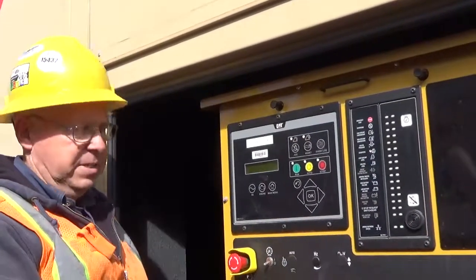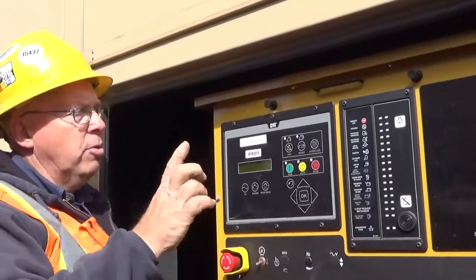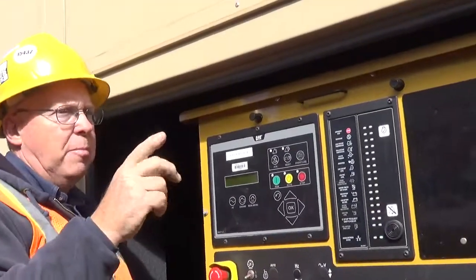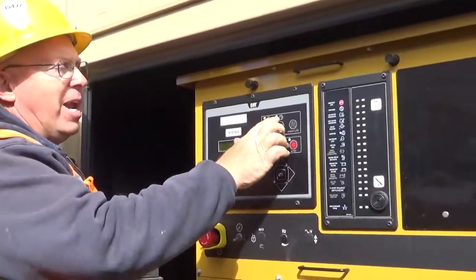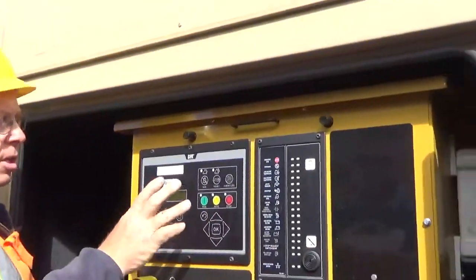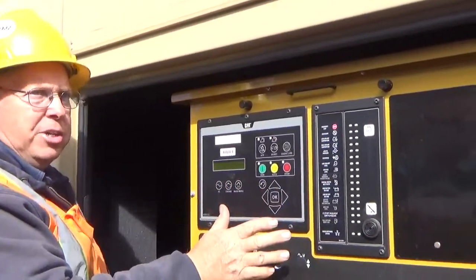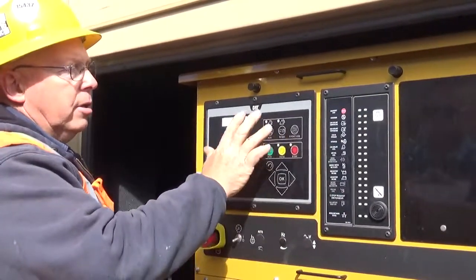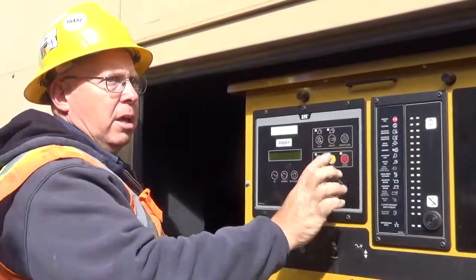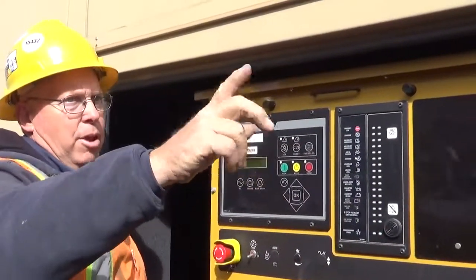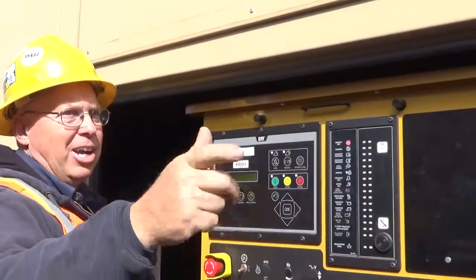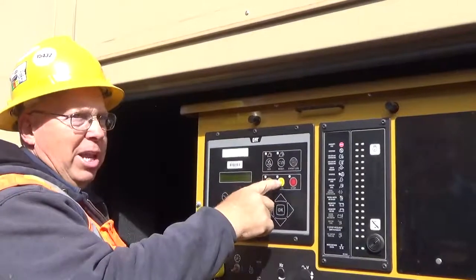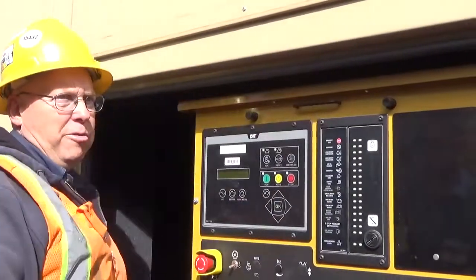Okay. Right? Yes. The biggest thing is, when he was telling you about it, if you have a shutdown where the red light is on, you need to, exactly right, correct the condition, figure out what it is, go to stop, correct the condition, then you have to go to him, put him in off reset, clear it, come back, put it in auto here, and then go put it in auto over there.